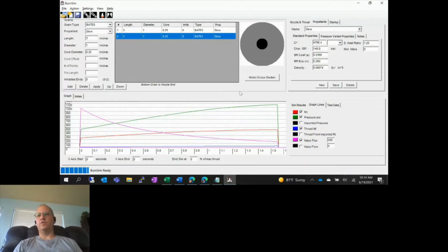A lot of the reasons behind that can have to do with particle grain size in the propellant, ingredients, burn rate enhancers, and that kind of stuff. Fortunately, in the short term, similar to KN, it's something you can watch for, where you start seeing burn rate changes based on mass flux.